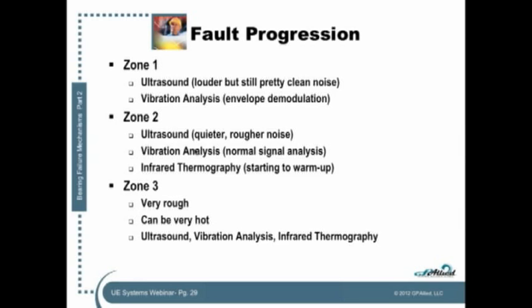Some bearings, those bearings that are locking up, will get extremely hot, which is why I don't suggest putting your hands on it. You can get a spot pyrometer now for $60, so no need to put your hands on something and risk getting hurt.